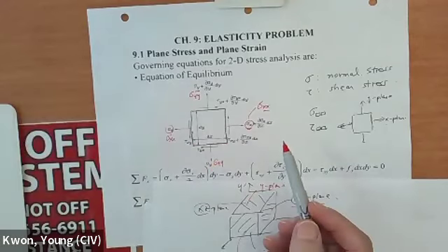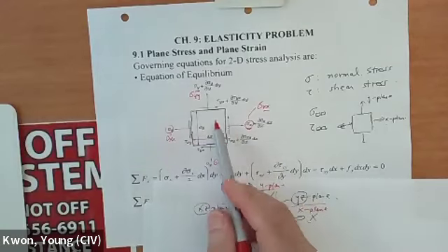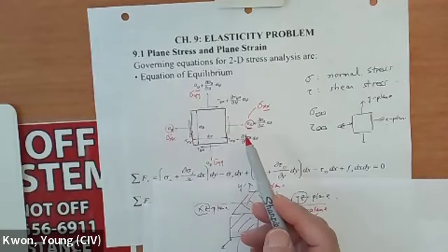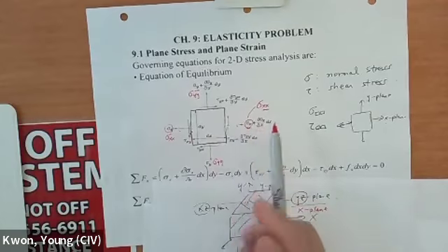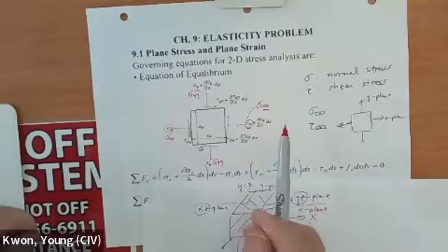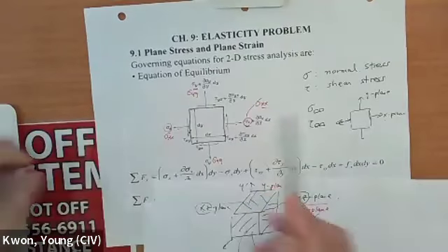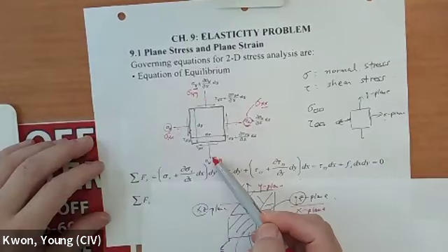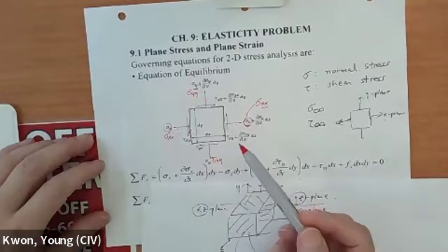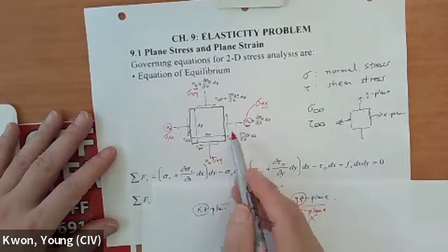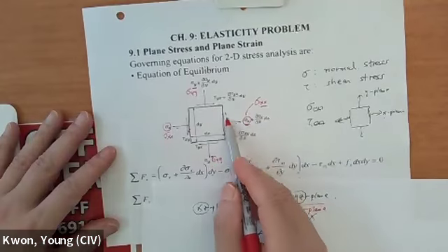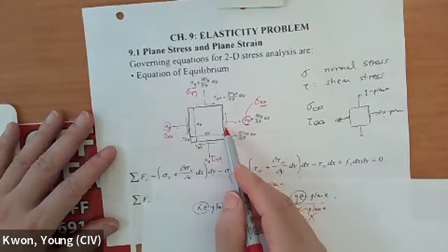Then what's the sign convention? You've got plus and minus X axis, plus and minus Y axis. What is positive stress? Which one do we define as positive, and which as negative? In this case, very obviously, tension is positive and compression is negative. So those are tensile stresses, so positive. This is positive. Okay, tension positive, compression negative. That is very clear.